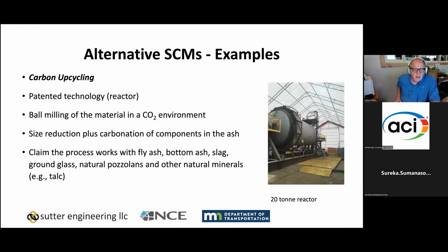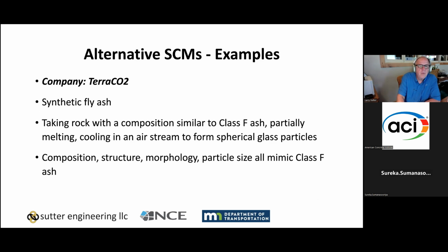The carbon upcycling is a patented technology. Again, they use a ball milling process, and the mill is pressurized with CO2. So they get the size reduction, but the CO2 carbonates calcium-rich phases in the ash. That embeds carbon into the material and gets embedded into the concrete. They state that the process will work with a number of different materials. In this particular case, we just tried it with the fly ash.